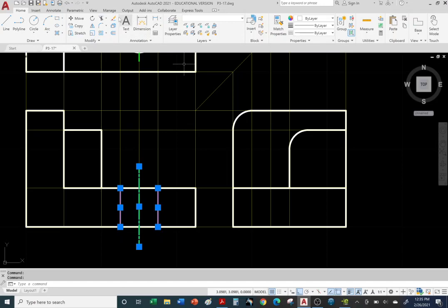All right, so let's go ahead and now let's use the copy command. So once again, copy command. I pre-selected the 3 lines first, right? Then I hit copy. And I need to grab a handle, follow the instructions. It's asking you, hey, grab it from a base point. So think of a handle. I'm going to grab it from here. Imagine a cup of coffee and you won't need to grab it from somewhere. Grab it from the handle. I'll pick this as my base point or handle point.